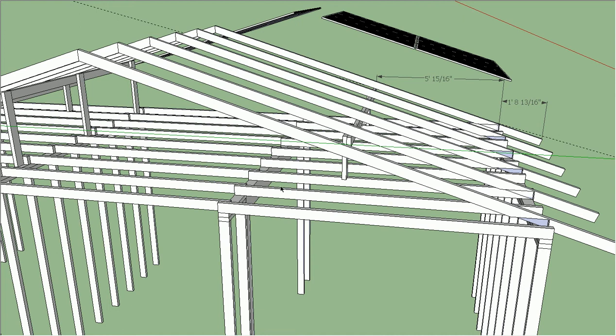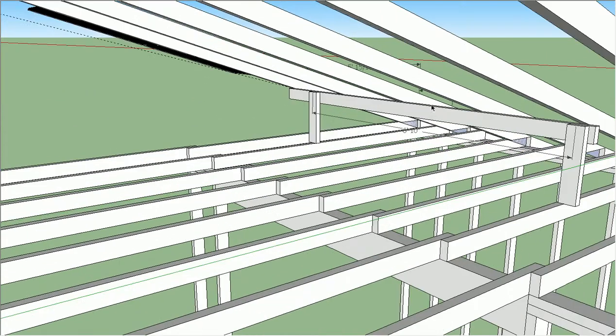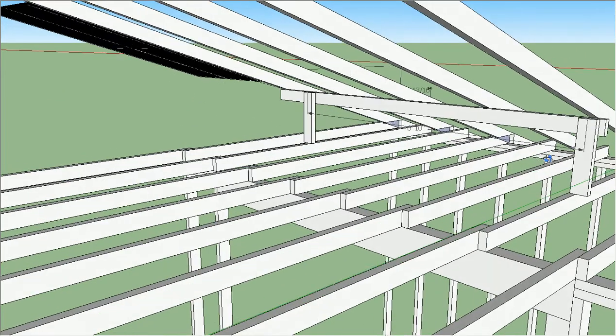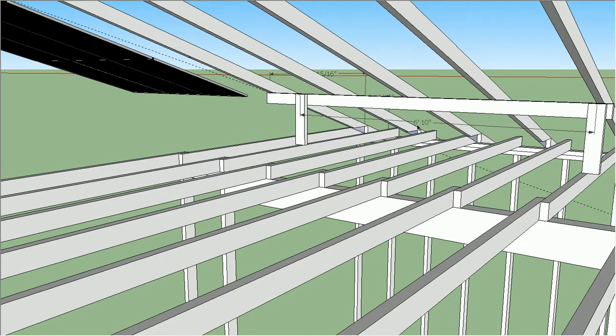There's another span here that isn't dimensioned. However, that's obviously not the only structural element that's receiving the load. This is a purlin type attic, which you see pretty commonly, and I've drawn in a 2x4 purlin here, and it's spanned 11 feet almost. And since this is a 2x4, it's very likely to be overspanned. This purlin is likely something that needs to be upgraded. And so, again, record the size, the spacing, and the span because the load hasn't yet made it into the wall.